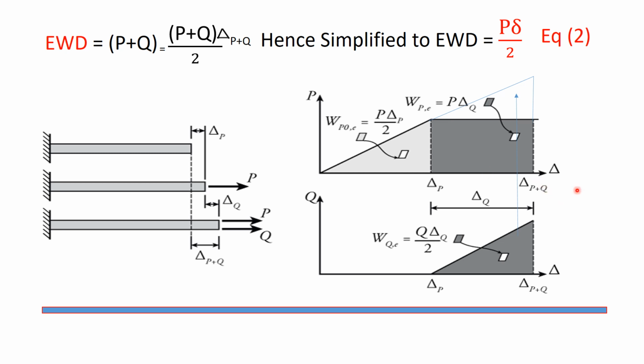Notice that in the type of work where the force doesn't cause the deformation, there is no more factor of half in the work equations. Since the area is rectangular instead of triangular, this distinction will be important in the development of the principle of virtual work. I mean, we have to add the triangular part into here, and then we get a linear form of deformation.